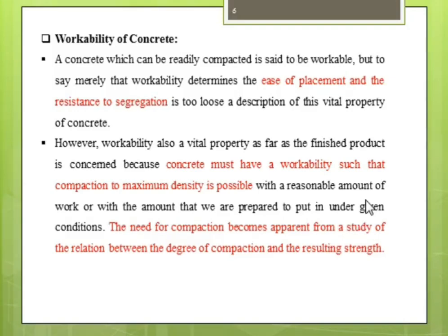If your concrete becomes harsh, suppose at a lower water cement ratio, this happens because free water is very less available for mixing of ingredients or for making the heat of hydration cement paste. The free water is very less at a lower water cement ratio. If you go towards 0.35, 0.3, 0.28 water cement ratio, your concrete will be very harsh.